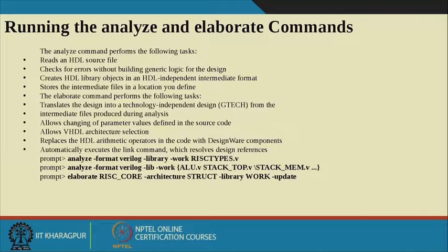After that, using read_verilog or read_vhdl, you can read any Verilog file or HDL file into the Synopsys environment. So after reading your HDL files in the Design Compiler environment, what you can do is run the analyze and elaborate commands. After reading the HDL source files, you run the analyze and elaborate command.